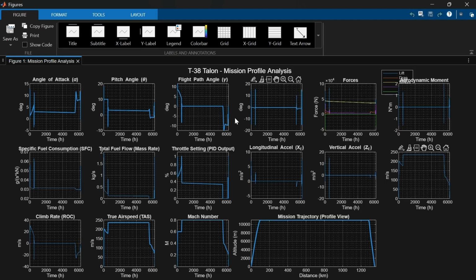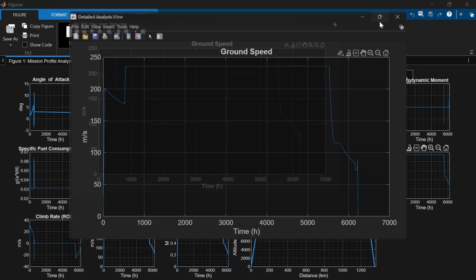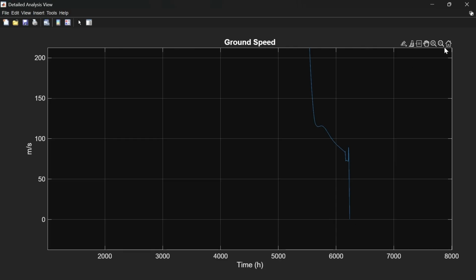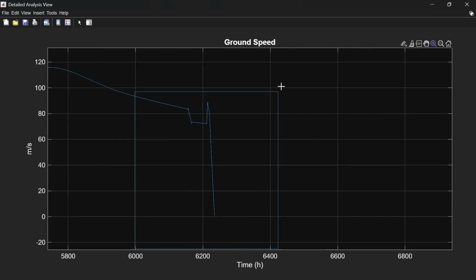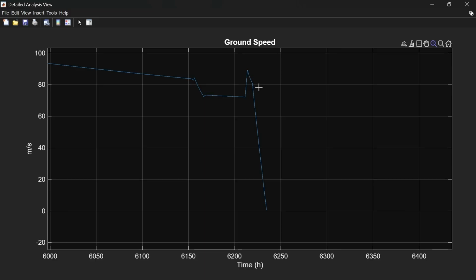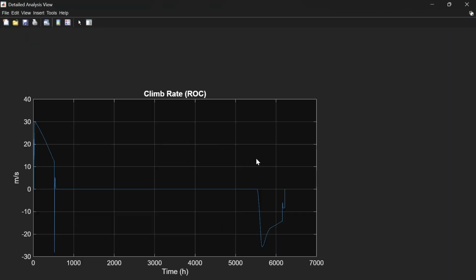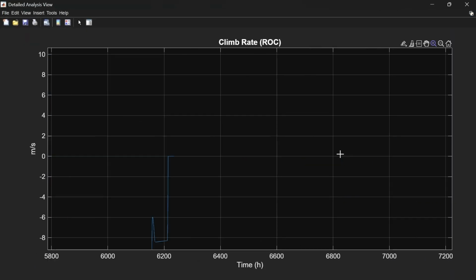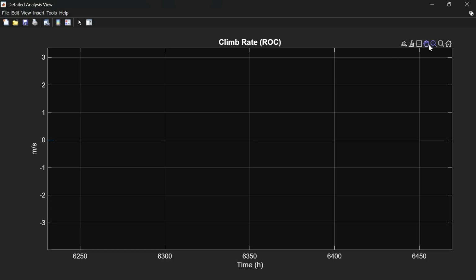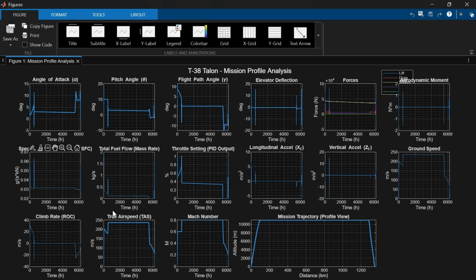Let's look at our ground speed. As you can see, it decreases to 0.5, like this. We have seen this trend already from the rotation part, and as you can see, it becomes aggressive because our brakes are active right now. This was the speed brakes, and these are the speed brakes plus my gear brakes. Climb rate, again, I expect this to be 0. Let's look at that. I went too much. Yeah, we're right.